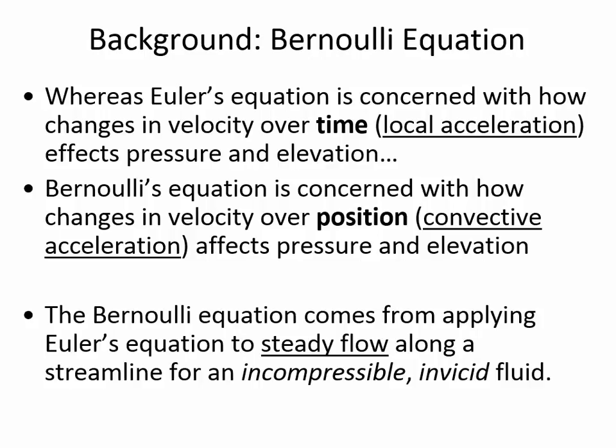And so this weakness of trying to model what's happening with the assumption that there's no fluid viscosity and therefore no friction losses, if we bring the 2 points closer together, then friction losses are minor and we get in less trouble for violating that assumption. So you can sometimes avoid the trouble of violating your assumptions by being selective in the circumstances that you apply the equation. So are there any questions so far?